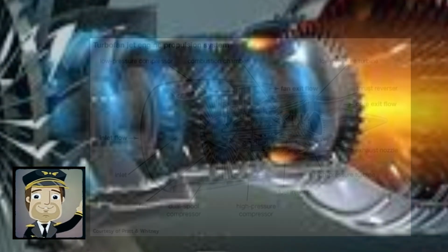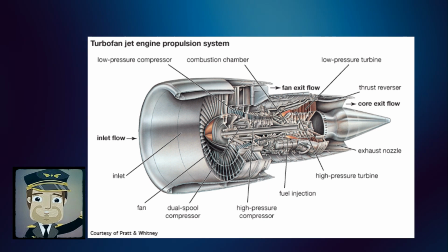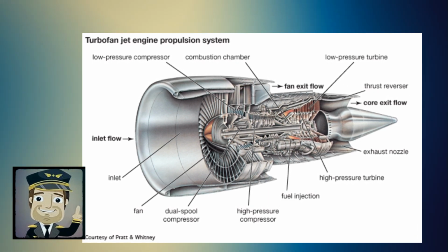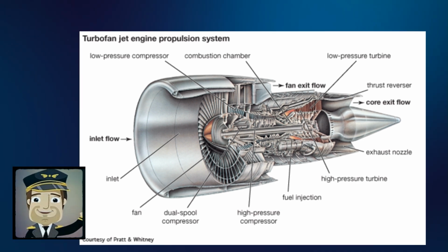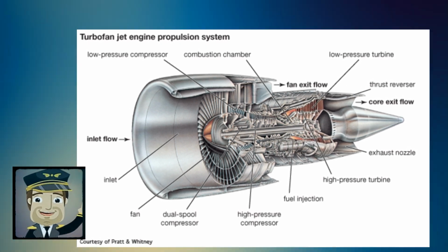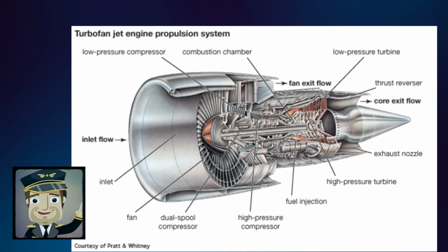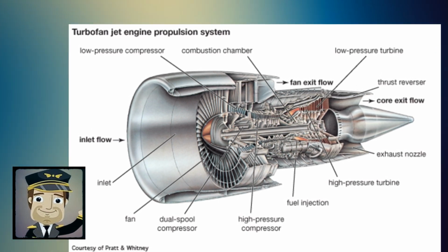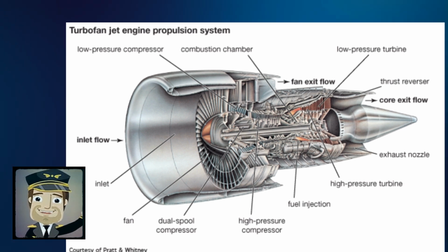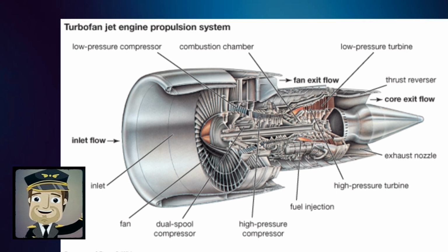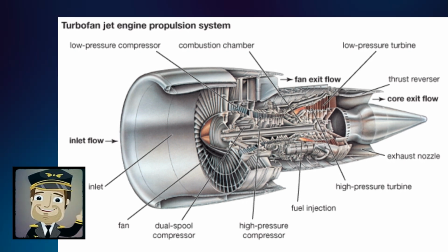Turbofans are closely related to turboprops in principle because both transfer some of the gas turbine's gas power, using extra machinery, to a bypass stream, leaving less for the hot nozzle to convert to kinetic energy. Turbofans represent an intermediate stage between turbojets, which derive all their thrust from exhaust gases, and turboprops, which derive minimal thrust from exhaust gases, typically 10% or less.